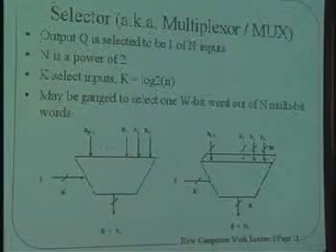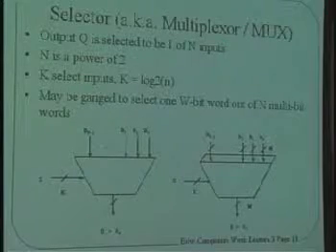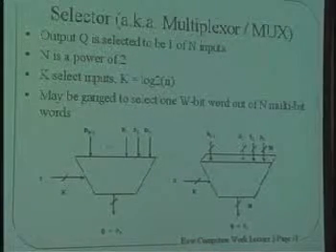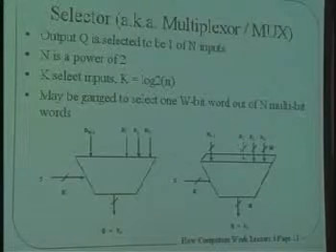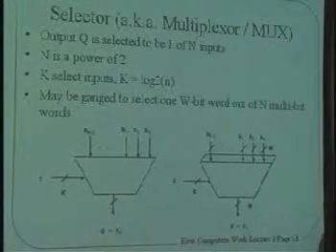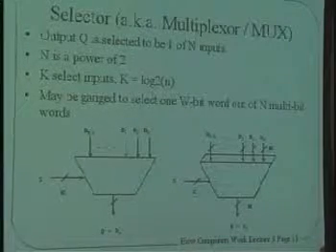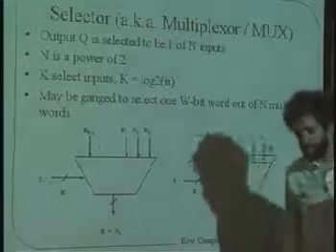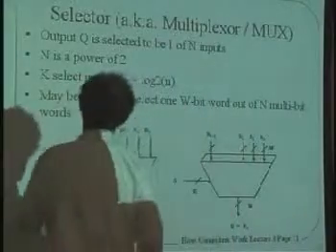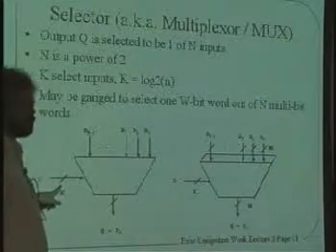So that was the hardest thing to get through, okay, if you understand how the registers work. Let's take a look at the easier things. These selectors, also called multiplexers or muxes, are used for choosing one of n different inputs for a particular output. The way that they choose it is based upon a select control, S, that comes in. And this may have several bits to it.